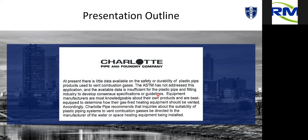They didn't want the liability because what happens with PVC is the melting point, and I'll sidebar and say the melting point, this is not taking a straw with a fire and melting away, disintegrating like you would think. It actually changes the molecular structure of PVC. It does have a kind of a yellowish brown tint to it. And people think you're burning the PVC. That's kind of what you're doing, but really what you're doing is you're changing the molecules to where it's no longer PVC. It's just a very brittle plastic. You can tap it with your knuckle and it cracks. Okay, so, but it goes through no listings, no testings of any of that sort.